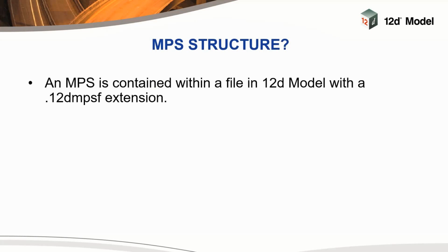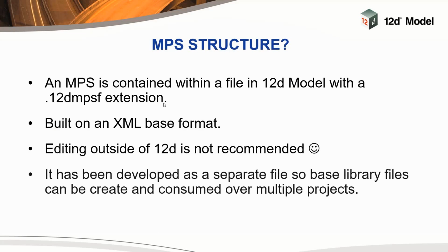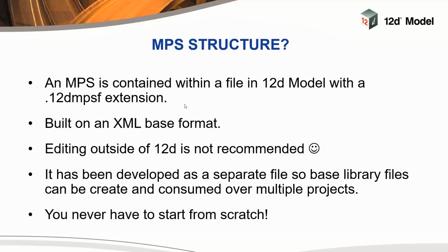So an MPS is contained within a file in 12D Model with the 12D MPSF extension. It's built on an XML-based format, but we do not recommend editing outside of the 12D Model MPS interface. It's been developed as a separate file, so these base files that you might set up for different operations within your industry or within your workflow can be saved as library files and consumed over multiple projects. So you never have to start from scratch, which is the most important thing.